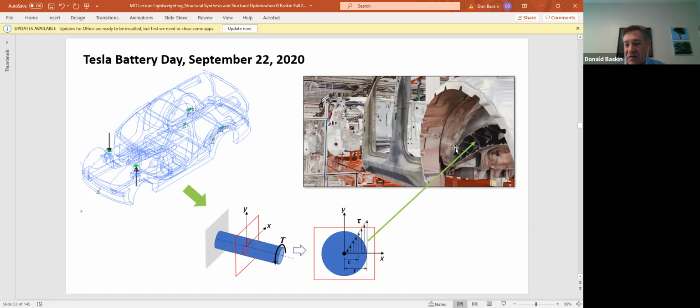It makes that panel stiffer using the laws of bending that we discussed last time, where the stiffness goes up with the cube of the height of the piece in bending, of the beam in bending, or in this case a panel in bending. And he's going to use the battery structure, the steel cans that make the batteries, to separate out those floor skins, so that the part will be stiffer and lighter.